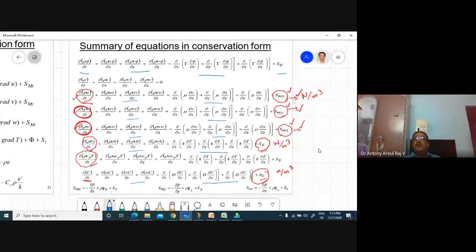So the reason for fluid to flow is these source terms. Just now I told you what are all the possible source terms in the momentum equation: adding, removing source, in X, Y, Z. There are two other sources which are responsible for creating the flow inside the domain. Those are the pressure gradient term, and then the body force term. So this term is a pressure gradient term.